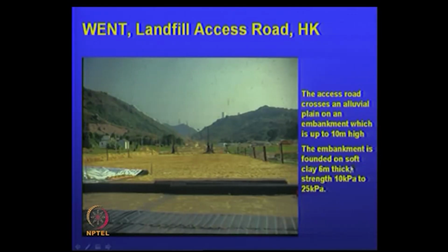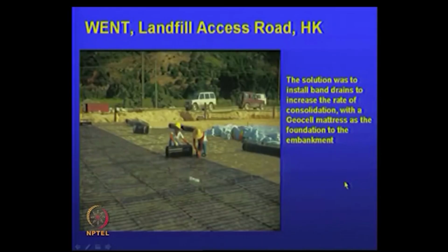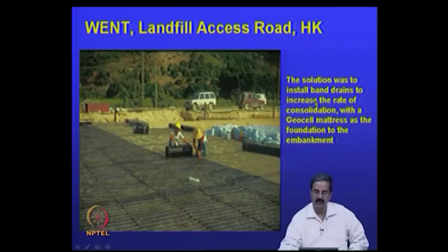The embankment is founded on soft soil of 6 meters thick, and the shear strength is 10 to 25 kPa, quite a low number. And the solution they used was to install band drains to increase the rate of consolidation, with a geocell matrix here as a foundation to the embankment.